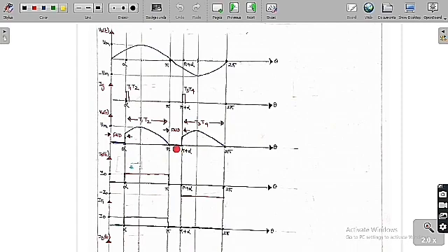So because of this reason only here the voltage is equal to 0. But in the full wave bridge rectifier here also T1 and T2 are going to conduct. But in this case the freewheeling diode is going to conduct. So because of that, from pi to pi plus alpha the freewheeling diode is going to conduct. So therefore the output voltage is equal to 0 and the source current is equal to 0.